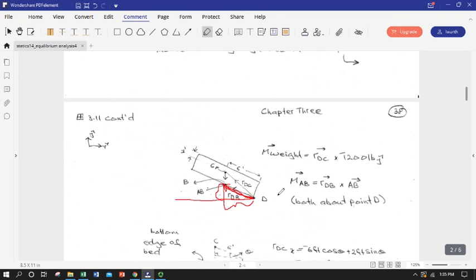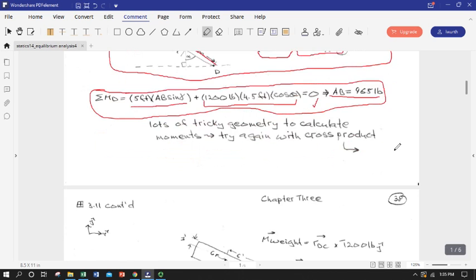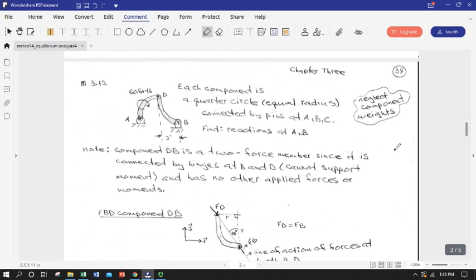And if you look at the answer that we got in the purely geometric case, it's pretty close. So that gives some confidence that we were doing things right. Okay, so you can step back through the geometry, lots and lots of right triangles. So right triangles are definitely your friend in finding dimensions and lines of action. You don't have to use vector algebra in a lot of these, but there are times when it can be helpful, like I showed, when you have easy ways to determine coordinate points.